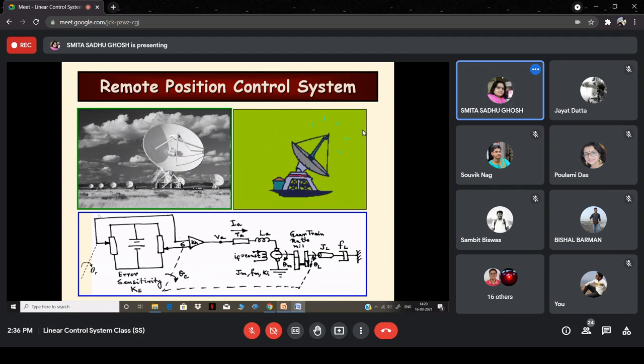To start with, first of all, over here in this diagram, you can see this unit. I hope you can see the cursor again. This unit is the potentiometric error detector. You can see that, right? You can see the two pointers here and there. And these elements, though they are shown as straight line strips, are actually circular elements because we are going to deal with angular position as far as this particular system is concerned. A more exact representation would have circular elements over here and there.